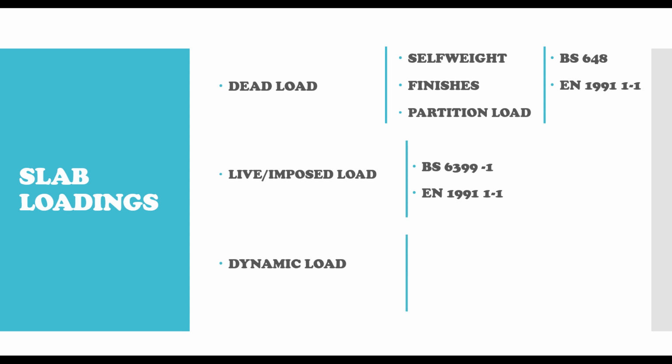You can find specifications on that, for the BS users, in BS 6399 part 3. But if you are using the Eurocode, you have to refer to BS EN 1991 part 1-4.